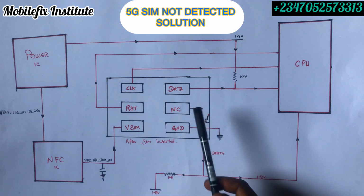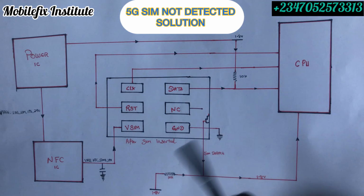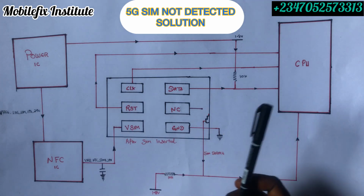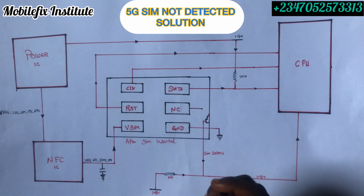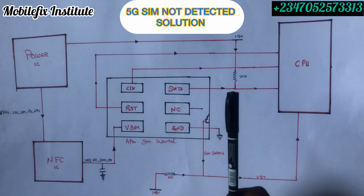If any of these pins has an open circuit, the line can break, maybe due to falling or anything can happen. Then any of these lines can break. If any of these lines breaks, it means that your phone will not indicate SIM. So you have to trace this line and then run the jumper.